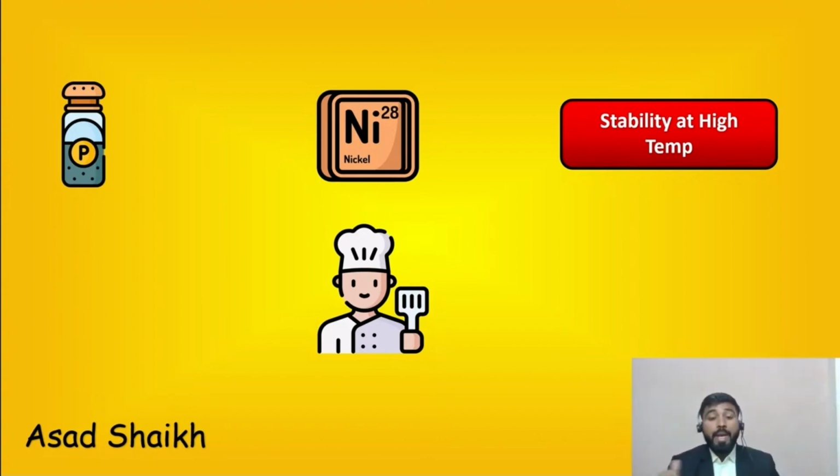Soft packing material. Now, packing material is a little bit trickier than this. I'll just give you thumb rules right now because we're running short of time. For packing material you need to see the fluid also. At the same time temperature becomes very important, and third is which Mayank mentioned, fugitive emissions. Overall, packing wise, for low temperatures, 200 degree, 250 degree, go for PTFE; for higher temperatures, 400 degree, go for graphite. If you have fugitive emissions, you usually start with first a V-type design, live loading design.